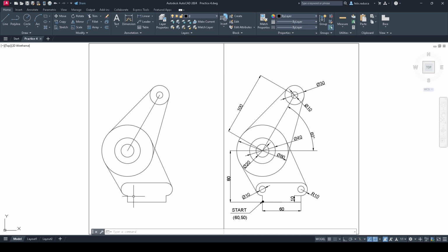So to do that, we give the circle command, then CEN and tap the arc here and give the diameter, D enter 10, and repeat the last command by hitting enter, then CEN, enter, touch the arc, and then D for diameter and 10, enter to finish the drawing.